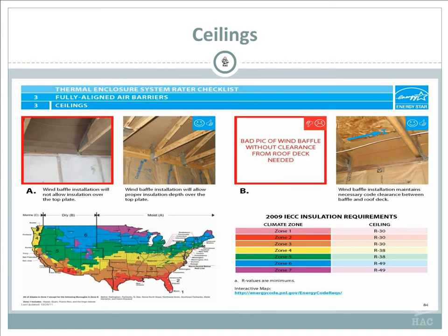The next one, you see where the baffle is above the insulation, so that's going to leave you space for that air. All you need to think about this is just a cardboard piece that is stapled to this 2x4, and then it's stapled to this 2x4 on the bottom, and on the outside of this is a vent. So when that vent draws air, or it blows air through there, it's going to go up this baffle, and it's not moving the insulation around here.